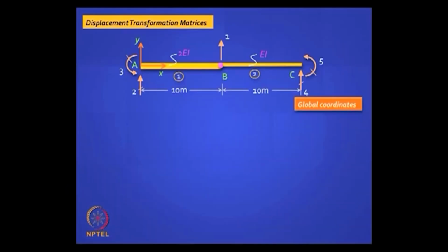Okay, ideally we should show a hinge also at B to remind us. Okay, the other coordinates are clear. So the coordinate 2 now shifts here, 2 3 4 5. So 1 active degree of freedom, 4 restraint degrees of freedom, same methodology.